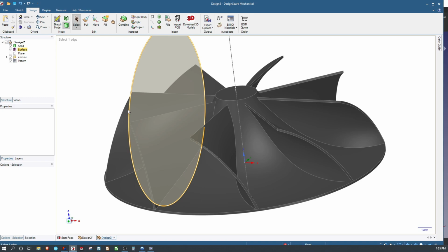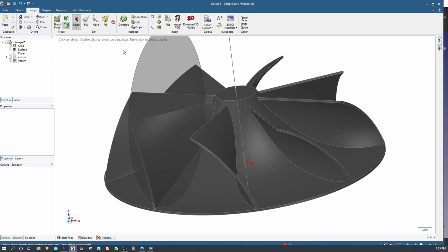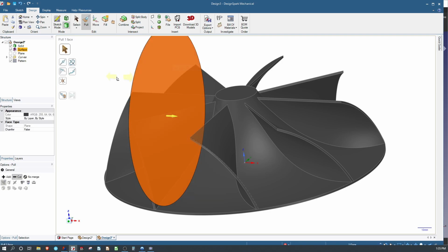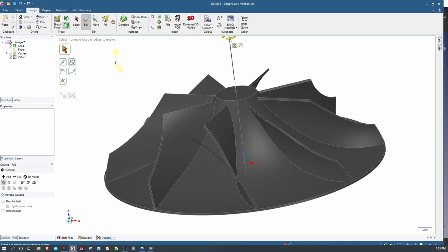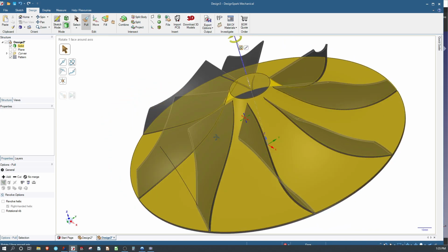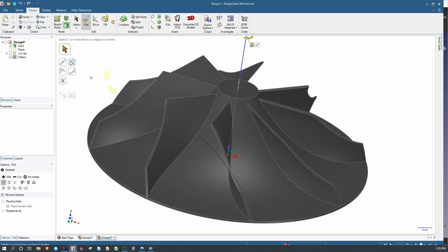So yeah. Let's now do a pull, and let's do a pull cut. So I'm going to move to my pull tool, right click, and choose this little minus sign for cutting material. We'll choose revolve, and I'll choose this axis to revolve around. I'm going to hold my mouse down, and as I start to go around here, I'm going to type 360, unclick my mouse, and hit enter. And now we've got a great little profile that we are cutting out of our blade, right? It looks a little bit more like a compressor.